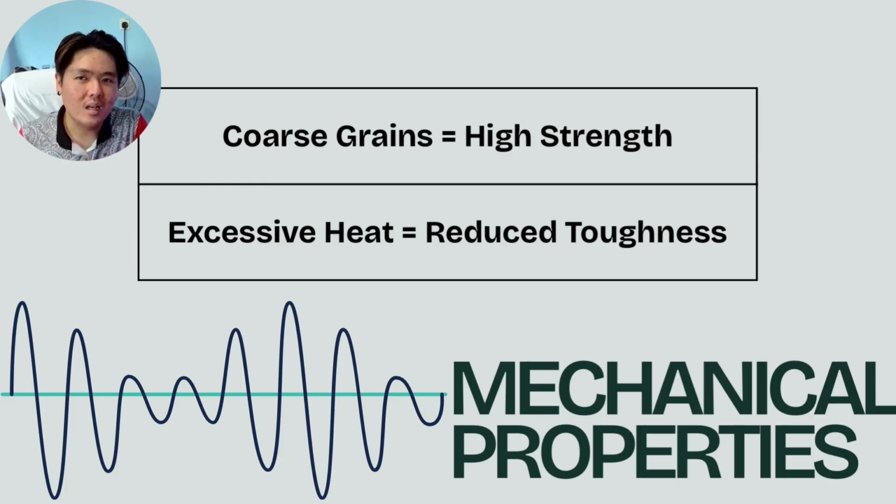So, in my opinion, for these mechanical properties, for welding especially, it is heavily dependent on your welding skill. There are many theories, but at the same time, you need the technical skills and practice to create a good weld. Like we said earlier, the correct welding technique. Maybe you didn't let the weld rest enough. Maybe also you are using a low current, or maybe you are welding in one spot for a very long time.